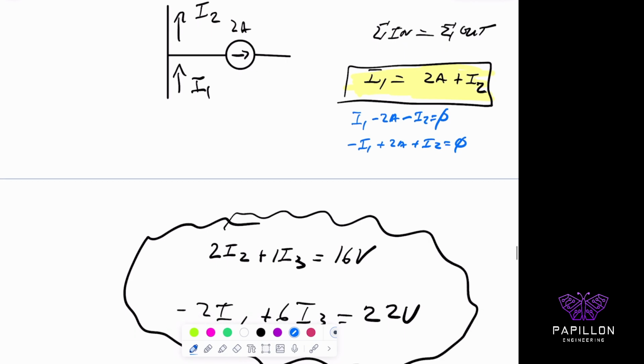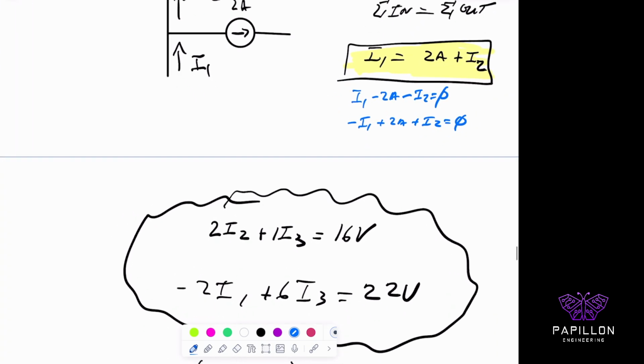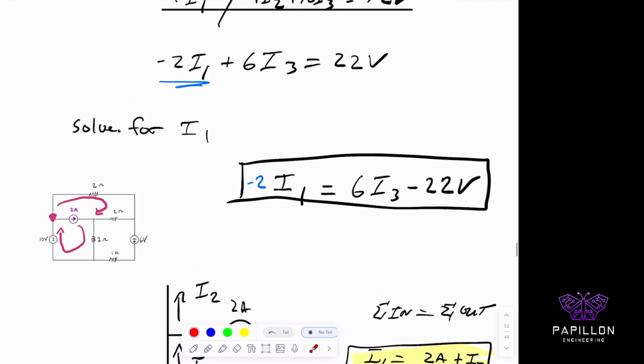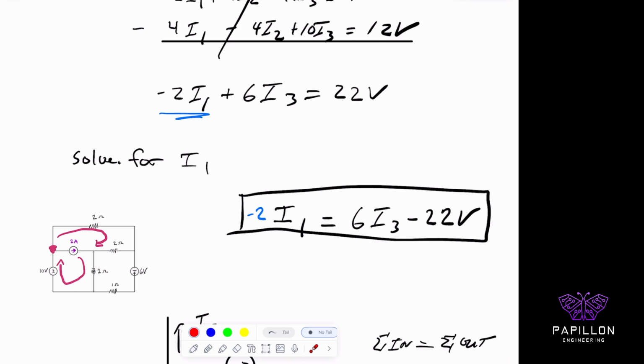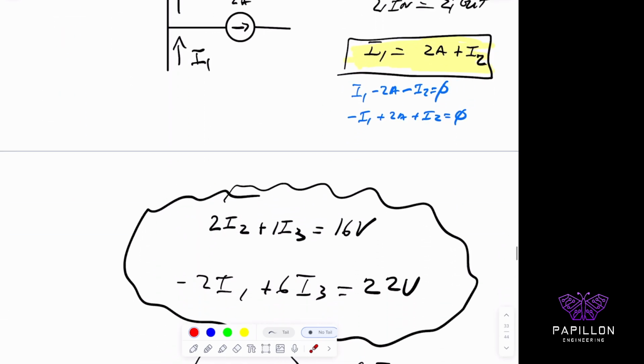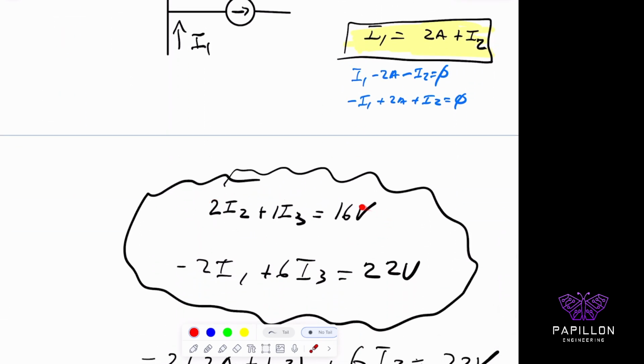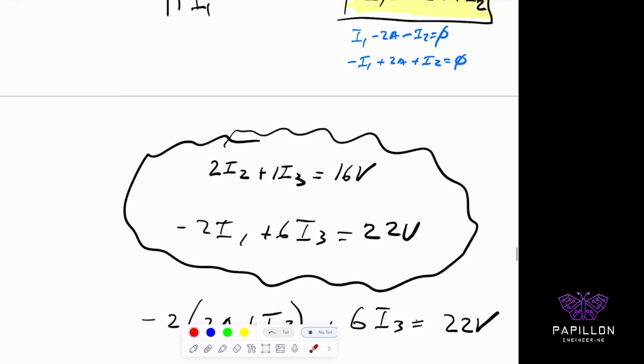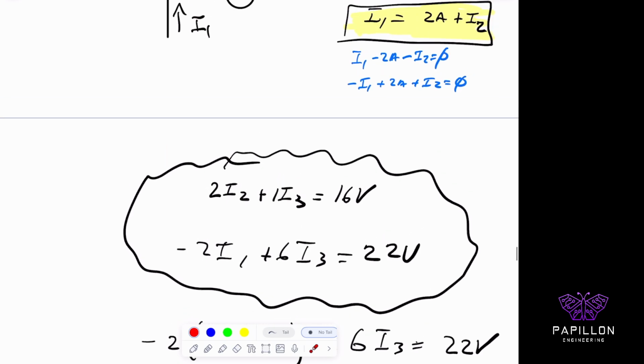So now that we have that, we have these simplified equations that I showed you before, right? And how did I get this equation? This minus 2I1 is from earlier. I tried to simplify these 2 equations to 2 unknowns by reducing one of these unknowns. So I have a simplified equation, minus 2I1 plus 6I3 equals 22 volts. And I did that for the other one as well, right? Because a 9 dropped out, and I'm left with this one as well. So now, I combine my constraint, which is, for example, I1. This is my new constraint equation, which comes from the KCL equations, right?